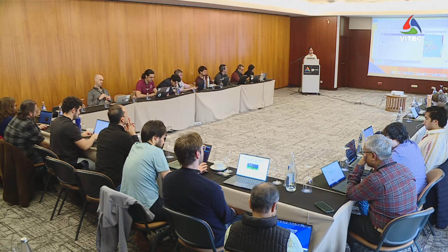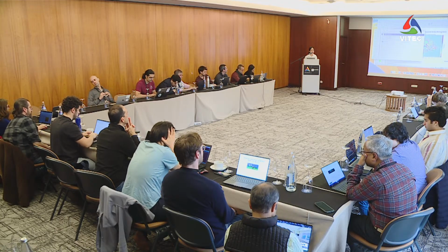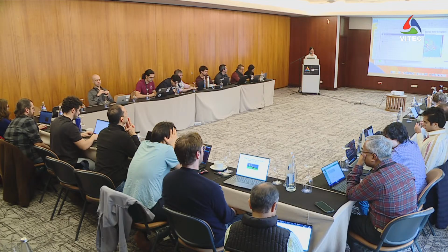You could assume those are, if you have a geocoded SLC, the same data format as this .int file. The extension doesn't matter; they all follow the same format. This 2.int file follows the single look complex format, which is the real and imaginary part. So you would read the same radar image and this interferogram the same way.